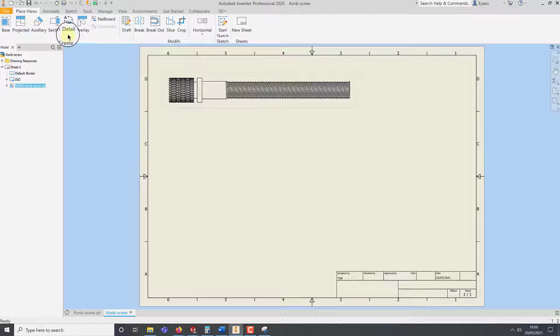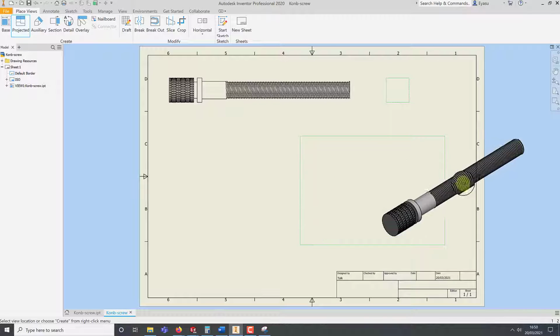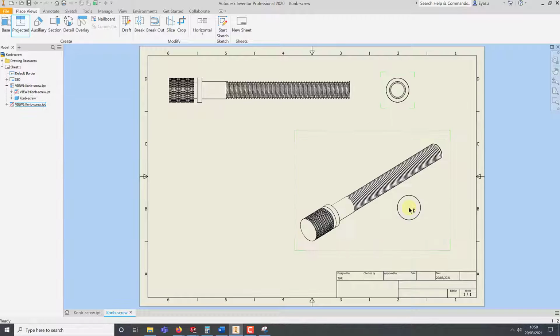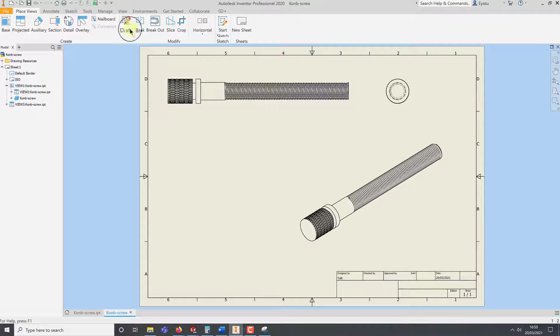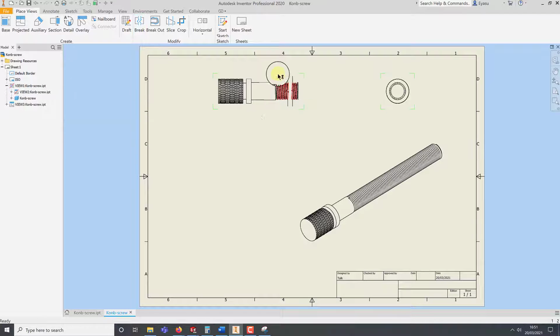To continue, what you need to do is projection, and it identifies that, and then isometric. Press enter, create. Okay, so this is too long, even this is too long, so we want to make this short, and I could use this tool called break. Based on that, somewhere here starting all the way to that point, I'm going to break it.